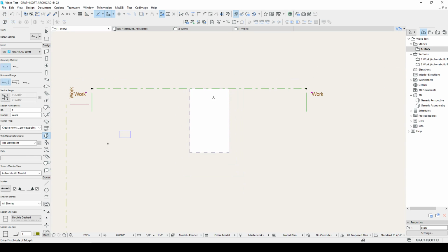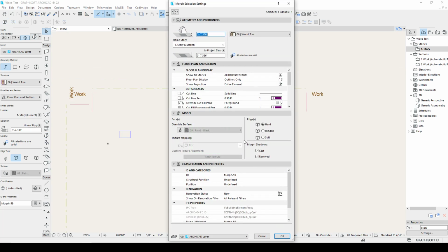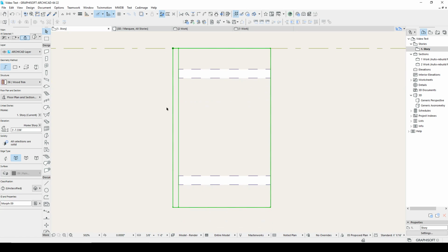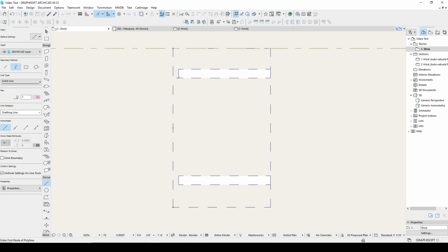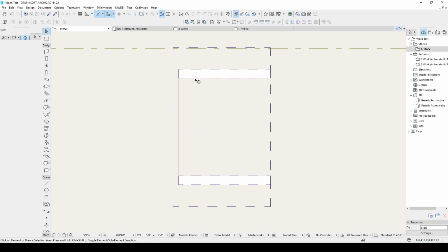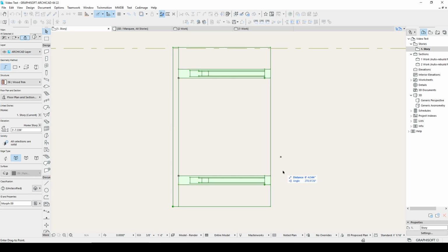And in plan, here I want to take the cover fill off so I can see through it, and then I can use a move tool, take the center of here, F5, and I like to use, the shortcut is a semicolon. Well, I'll just do it the easy way. I'll draw a construction line, F5, line up to that center, and now I have it centered in plan.